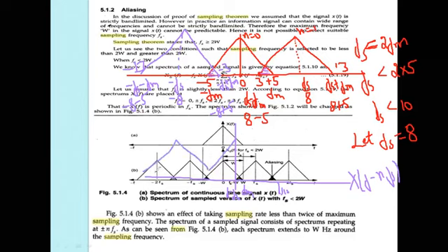Okay. There is a gap here. There is a distortion because of aliasing. What we are seeing is a distortion. Only up to this value is it recovered, but at the point where the overlapping occurs, it is not recovered. Understood, my dear students? So it is band limited to Fm hertz.